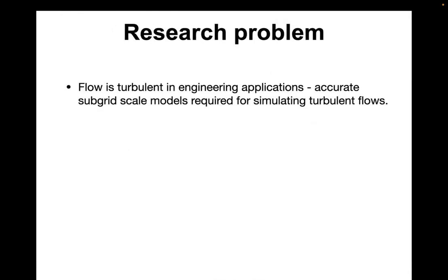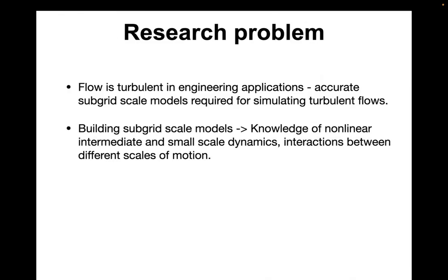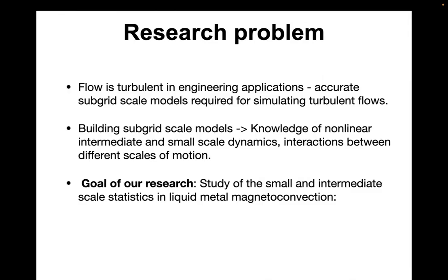Now, magnetoconvective flows in the above applications are highly turbulent. Hence, we require appropriate subgrid scale models for simulating such flows. Building such models requires detailed knowledge of intermediate and small-scale dynamics of turbulent flows, as well as interactions between the different scales of motion.